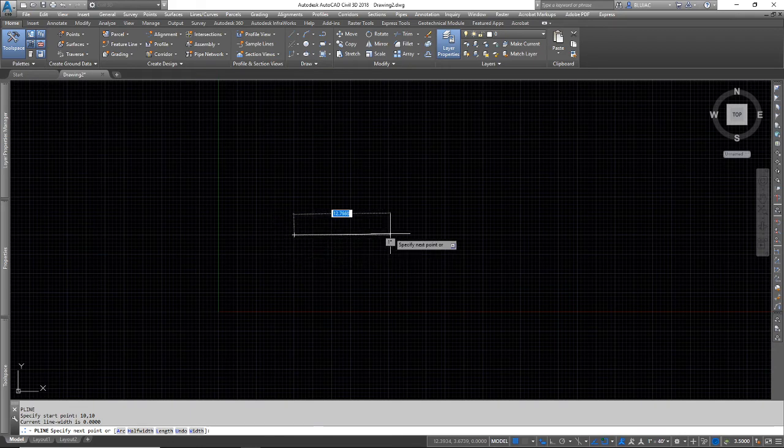I'm going to continue and create a 10-unit square relative to this first point that I input. If I was going to start my square by going 10 units horizontally along the positive x-axis and 0 units in the y direction, I'm going to input 10 units in the x direction and then comma 0 units in the y direction. When I hit enter, there I have my first line.